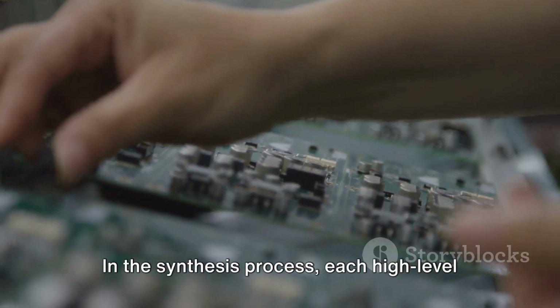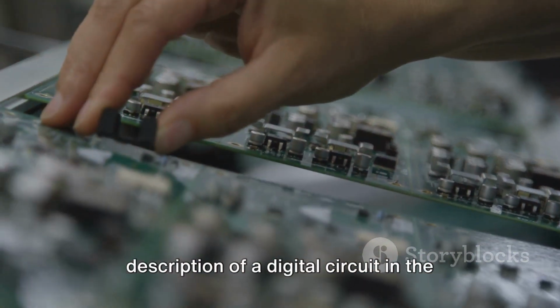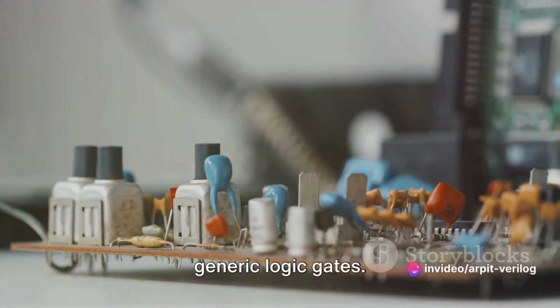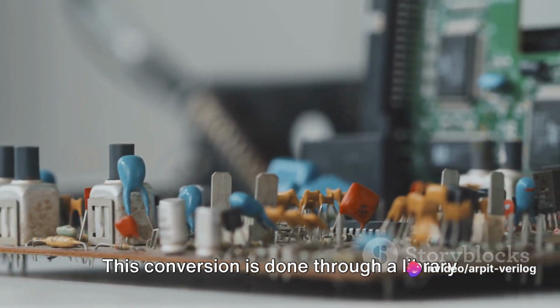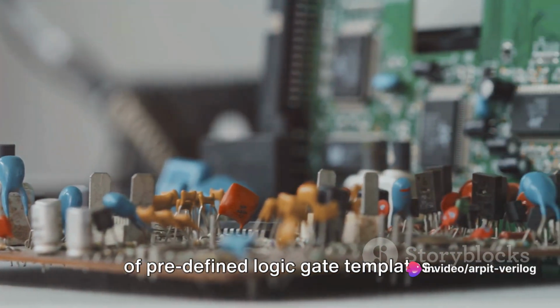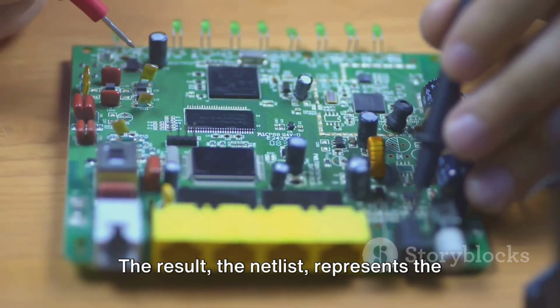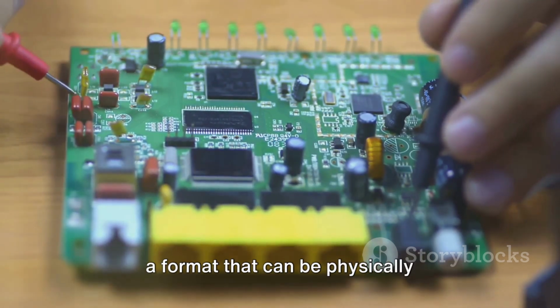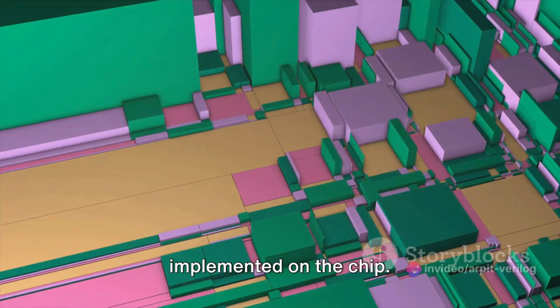In the synthesis process, each high-level description of a digital circuit in the RTL code is converted into a set of generic logic gates. This conversion is done through a library of predefined logic gate templates. The result, the netlist, represents the same functionality as our RTL code, but in a format that can be physically implemented on the chip.